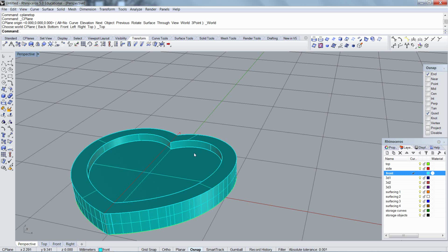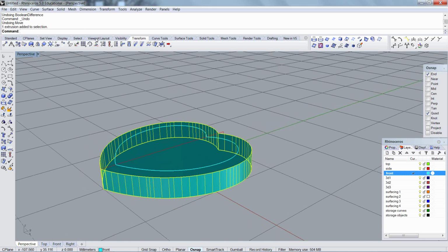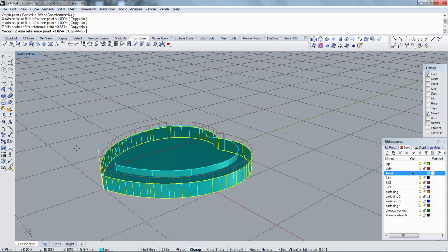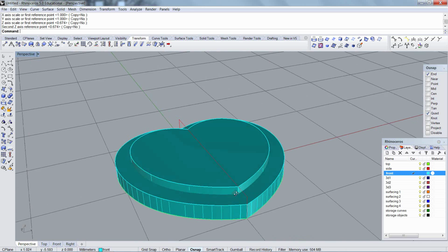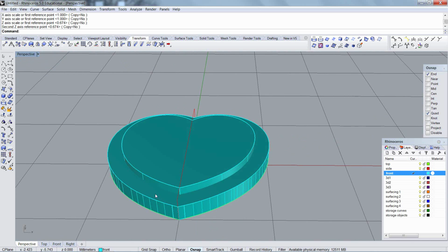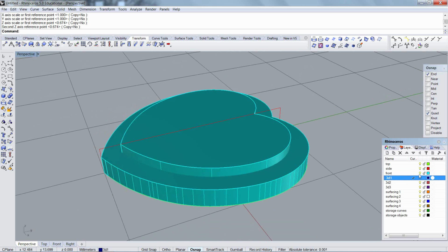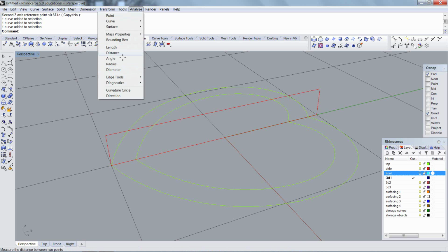Both of these things are typical ways of making a maquette using a simple extrusion. I'm going to go ahead and make the extrusion a little more sophisticated through the use of fillets. Okay, so I'm going to fillet this outside edge. Remember, the way to figure a fillet is to decipher what the distance is that you're working with, and then not go beyond half of that if you're going to fillet both sides. So in this case, analyze distance.